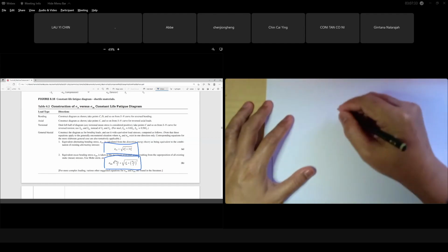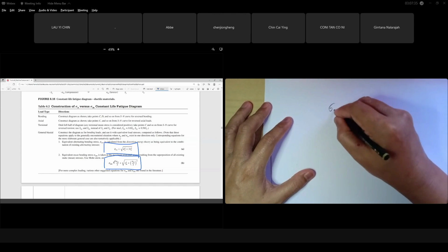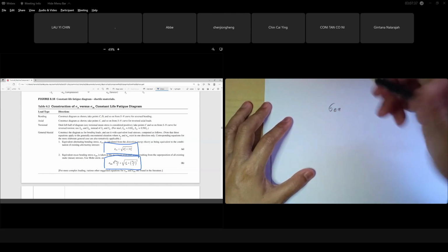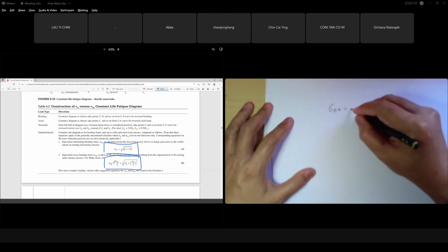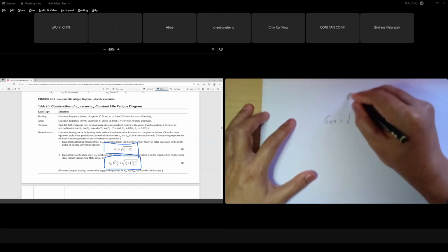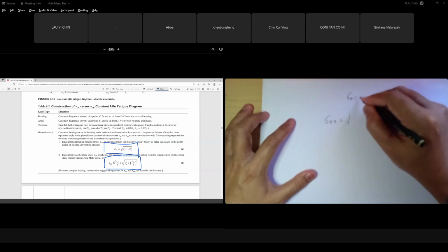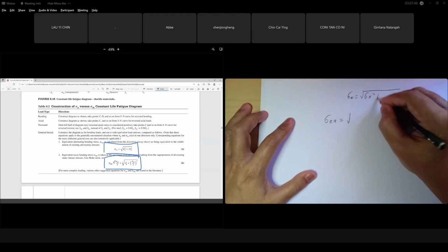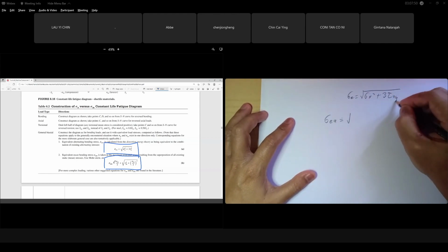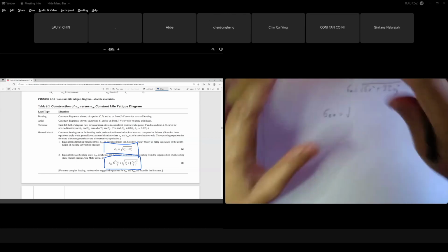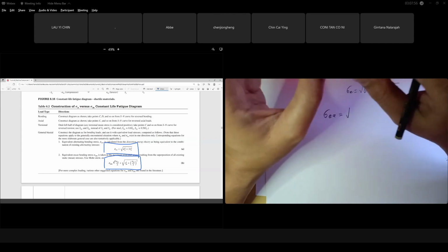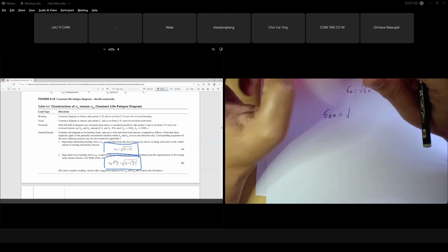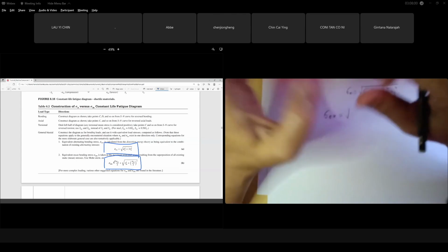The equation: when you calculate the sigma E amplitude, remember, if you have biaxial stress, sigma equivalent equals the square root of sigma x squared plus 3 tau xy squared. But here we have both, so you have to find the equivalent stress alternate, or amplitude, and also the equivalent mean.